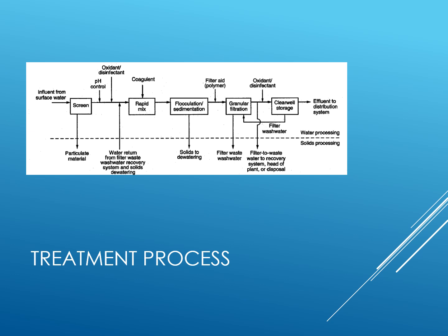Then there's filtration. The water is passed through filters to remove remaining suspended particles, including sand, clay, and algae. Common filter media include sand, gravel, and activated carbon. The next step is disinfection. Disinfectants, such as chlorine, are added to kill harmful bacteria, viruses, and other microorganisms. Other disinfection methods include ultraviolet, or UV, and ozone.